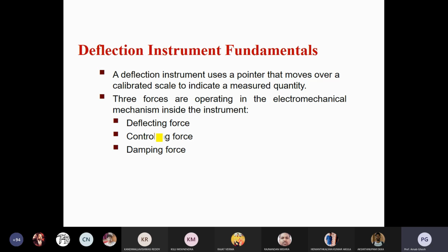You need to add some additional thing, like using some pistons just attached with the pointer, or some balance load, that can damp or die out that oscillation. That can die out the oscillations of your system. That's the basic reason for the damping torque in your instrument.